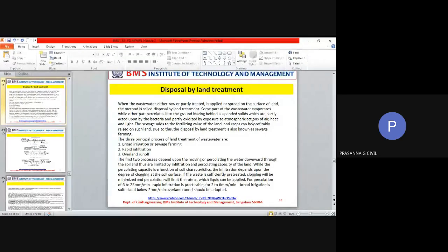But there is a by-channel. In the rainy season, water is coming from everywhere. They cannot handle it in their treatment plant. Their treatment plant is 120 MLD capacity. If excess water is coming, what are they supposed to do? Can this water be blocked anywhere and kept? No. So what will they do? They will have a bypass here and some amount of this will enter. Got it?